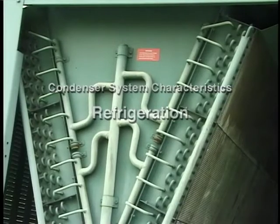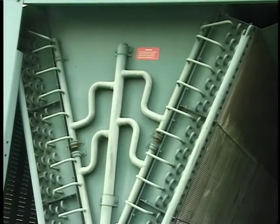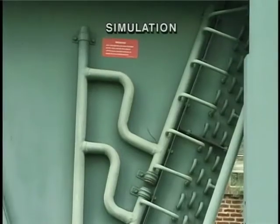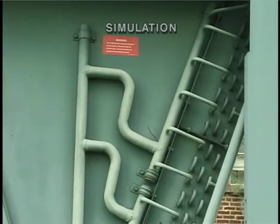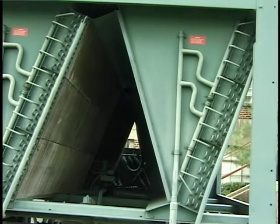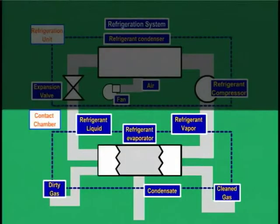Refrigeration systems use compressed coolants and operate at temperatures as low as -150 degrees Fahrenheit. The most common coolants use CFCs, although this is changing in response to the Clean Air Act amendments of 1990. The refrigerated liquid, flowing through tubes in a shell and tube heat exchanger, absorbs heat from the gas stream flowing on the shell side, reducing the gas stream temperature and causing the contaminant to condense.